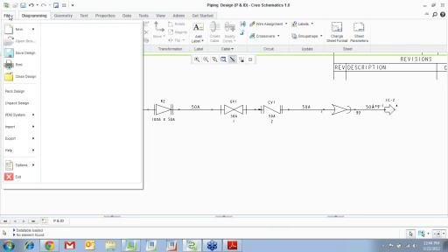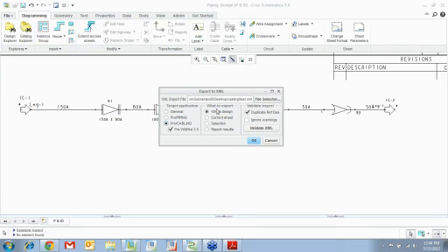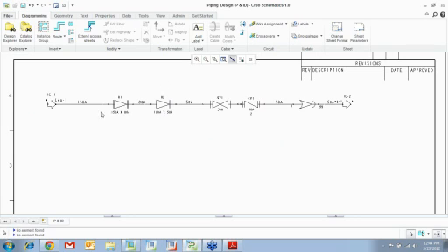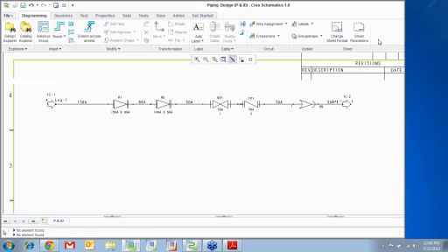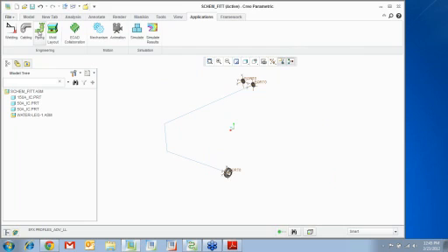So once you do this, you're going to export it as an XML file, right? And you want to say Pro Cabling, and you say OK. It's really, really simple to create these little cables and wires in the 2D. All you do is pick and place the symbols, select, right click, go to properties, and apply a data set. And that data set is a one-time thing that you load. It's always there. So you don't have to remember, oh, what size Pro E part do I use for this particular symbol. All right, so once that thing is done, you want to go into cabling, piping.